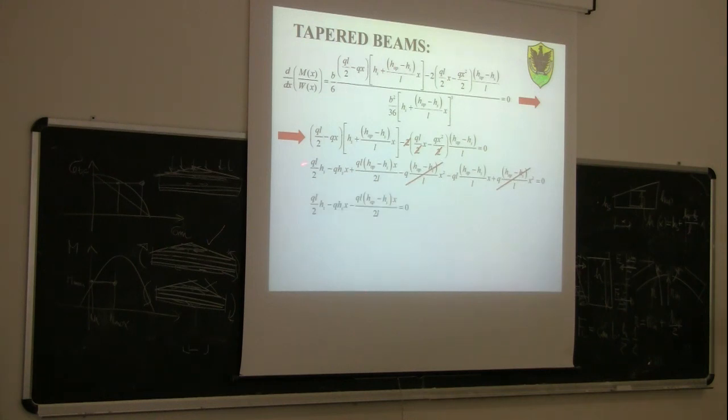This relationship here is again equal to 0 when, again, X here is given by L in the end. X is equal to L over HS plus HAP divided by HS. So the maximum of the sigma will be at the cross section given by L over 1 plus HAP divided by HS, which is in general not half of the length. Okay?